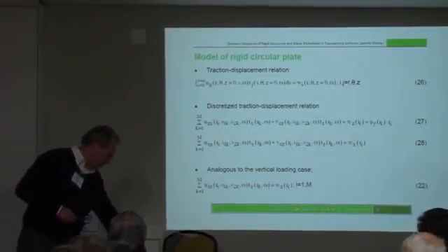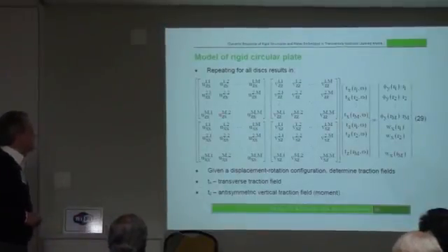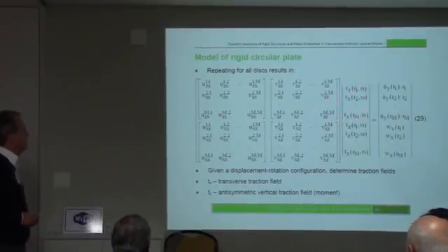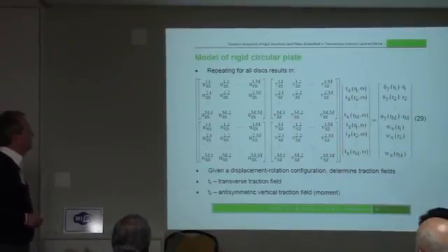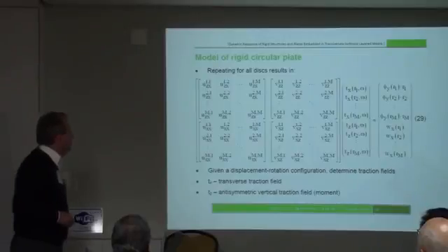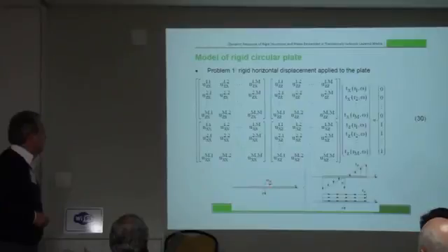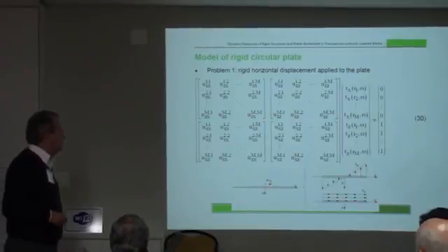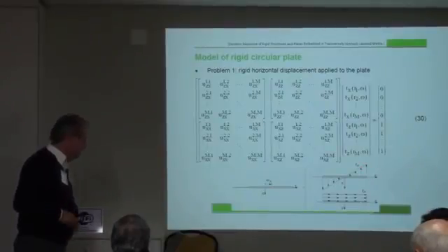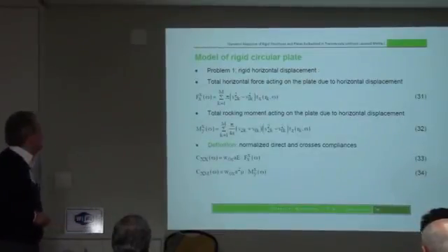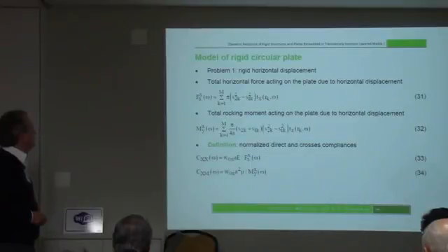We have a classical discretized system with tractions in horizontal, tractions in the z direction, and you can find the solution to tractions here by imposing the displacement conditions there. It's not new. So we can pose horizontal displacement and find forces, tractions in the z, and then x direction. It is all very classical. We have to add equilibrium in the horizontal direction, moment equilibrium as well.